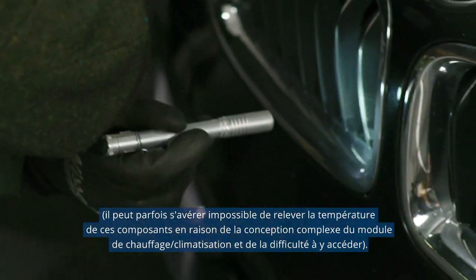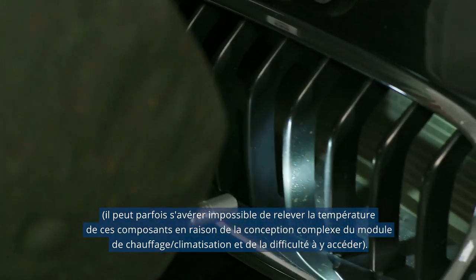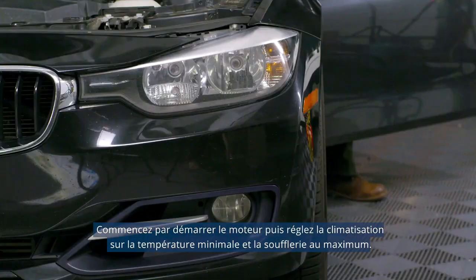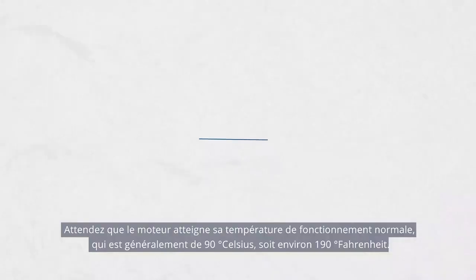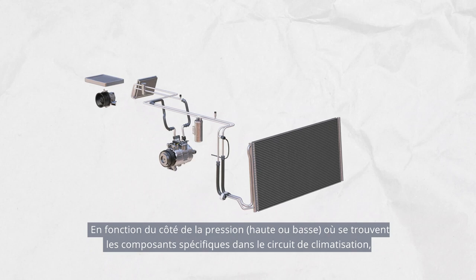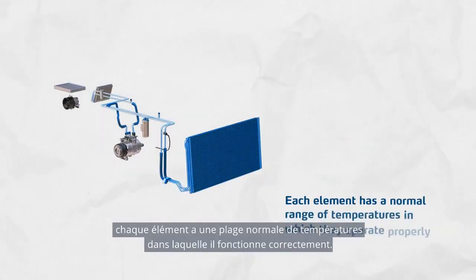But sometimes it can be impossible to take a measurement of these due to the sophisticated design of the HVAC module and difficult access. First, start the engine and set the AC on to the coldest air and maximum blow. Wait until the engine achieves its proper operational temperature, which is typically 90 degrees Celsius or around 190 degrees Fahrenheit, and you're good to go. Depending on the pressure side where the specific AC loop components are located, each element has a normal range of temperatures in which they operate properly.